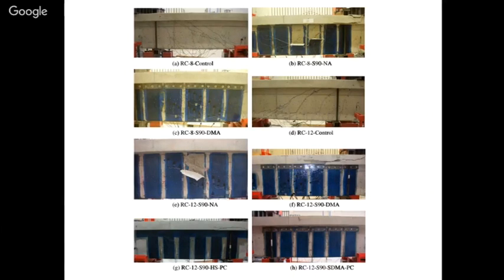When the entire beam deforms to a large extent, what will happen? The FRP will come out. That is generally referred to as debonding failure, delamination from the surface. If your FRP delaminates, then we can't attain the entire strength, or the performance level is not attained. In such a case, we have to provide end anchorage to the FRP. You can see in the third image, they have provided additional end anchorage in all the FRP strengthened parts. So all the FRP strengthened beams with end anchorage show no evidence of delamination. When you go for FRP strengthening without end anchorage, you can see delamination.